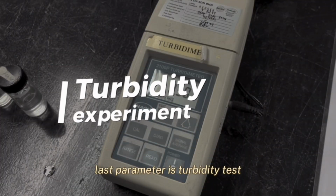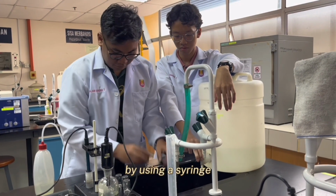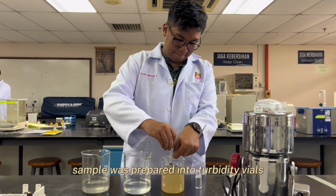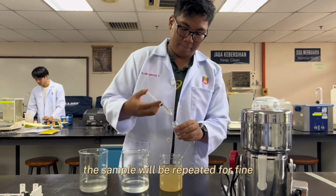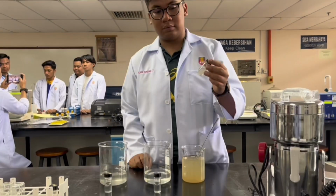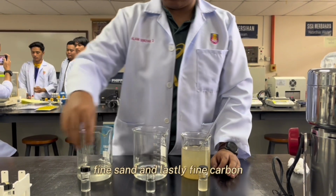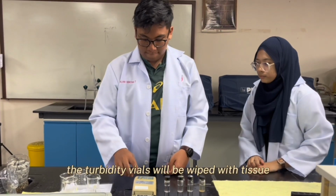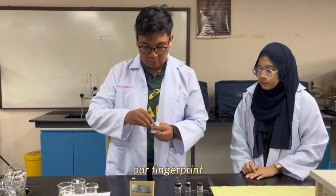Last parameter, turbidity test. By using a syringe, 10 ml of water sample was prepared into turbidity vials. The same will be repeated for fine sand and fine carbon. This is the raw water sample, fine sand, and lastly fine carbon. The turbidity vials will be wiped with tissue to prevent errors from our fingerprint.